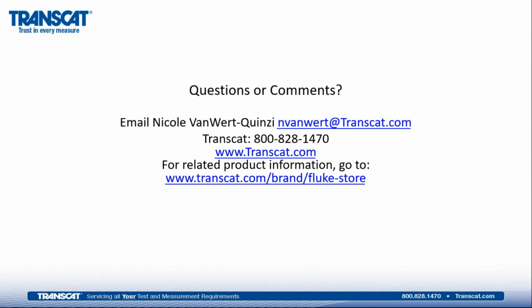In the case of an RTD, it's a little bit of a misnomer to say it's a signal, but it's actually a changing resistance. RTDs do also have lookup tables, resistance versus temperature, and by measuring the resistance of a particular sensor, if you know the sensor type, for example, PT100 385 is the most common process sensor for RTD.